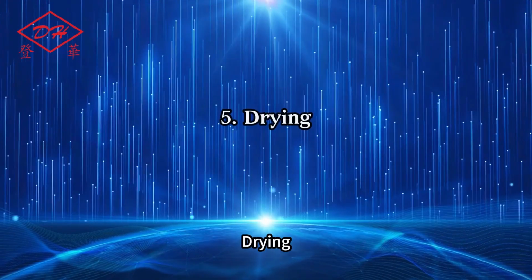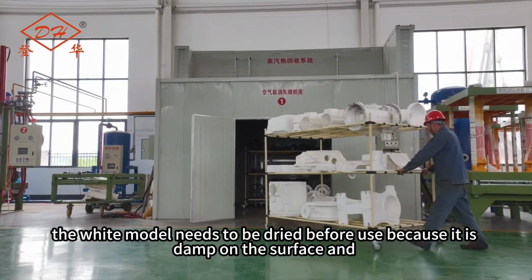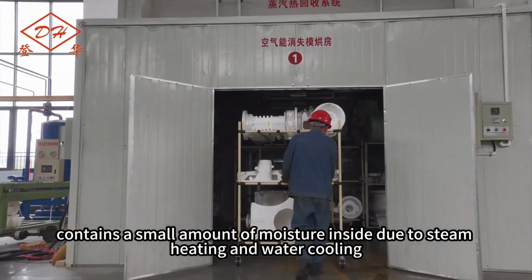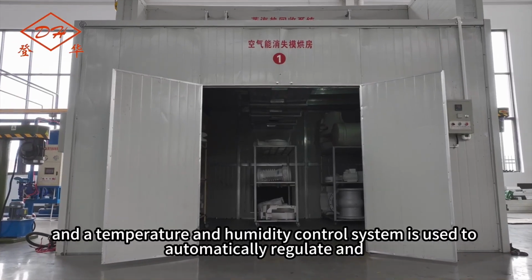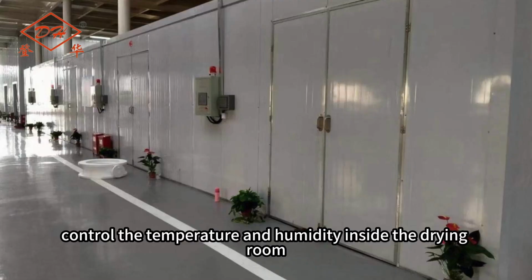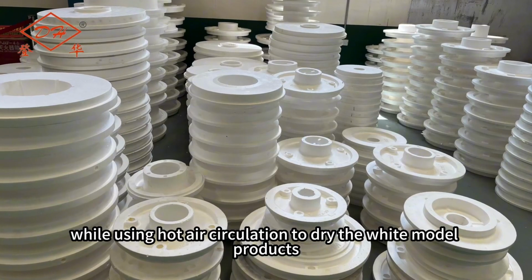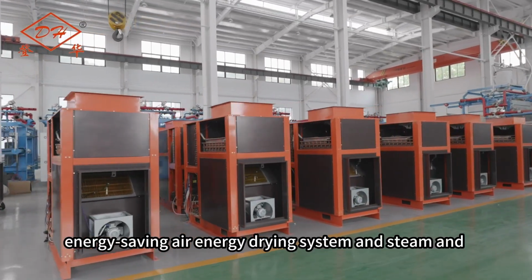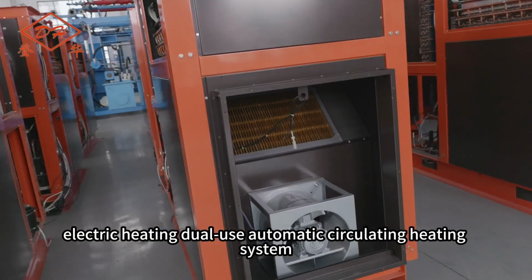Fifth, drying. After shape molding, the white model needs to be dried before use because it is damp on the surface and contains a small amount of moisture inside due to steam heating and water cooling. The white model is placed in a drying room for drying, and a temperature and humidity control system is used to automatically regulate and control the temperature and humidity inside the drying room, while using hot air circulation to dry the white model products. Our company produces two types of drying room heating system: energy-saving air energy drying system and steam and electric heating dual-use automatic circulating heating system.